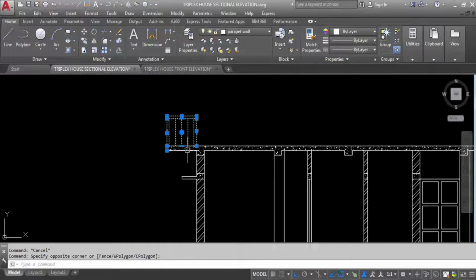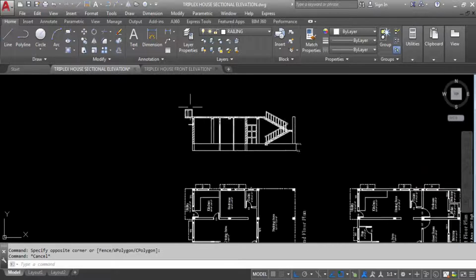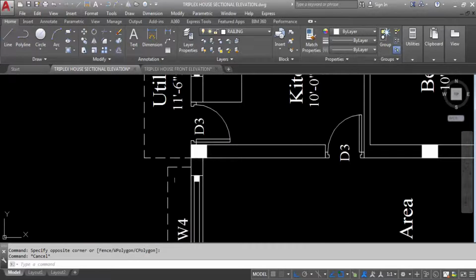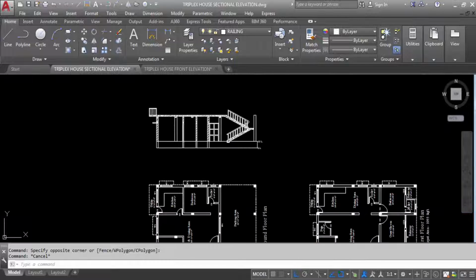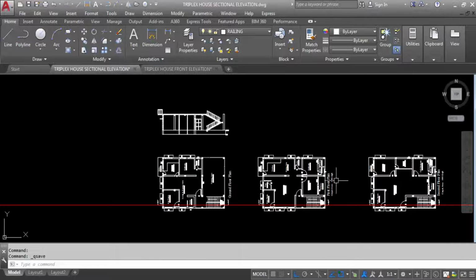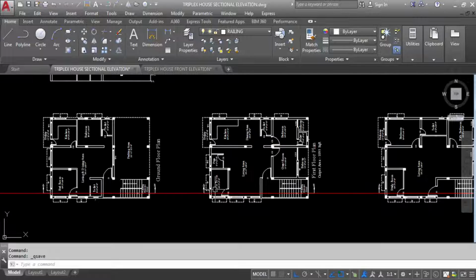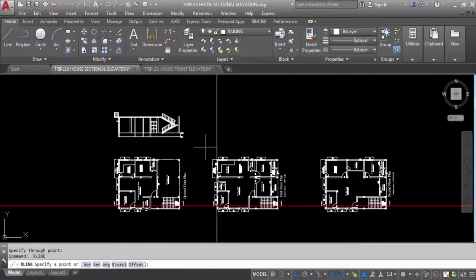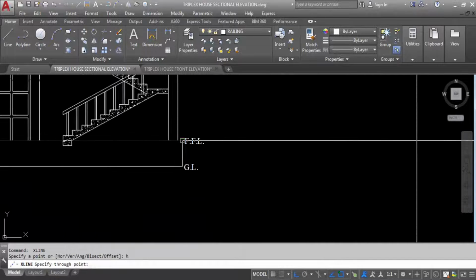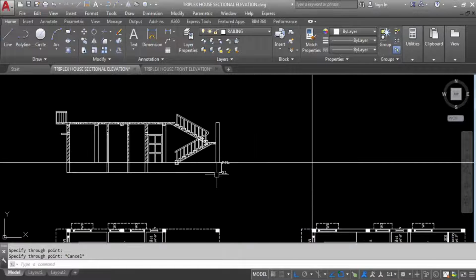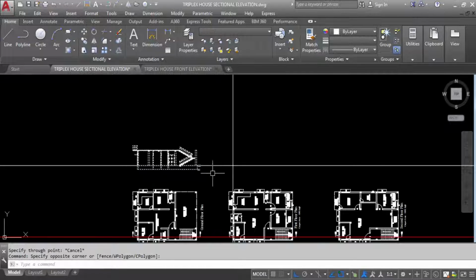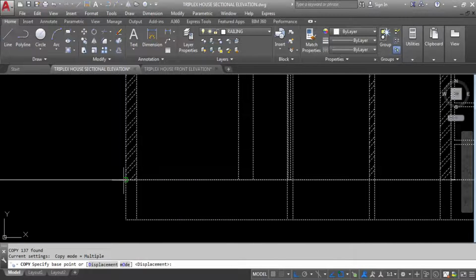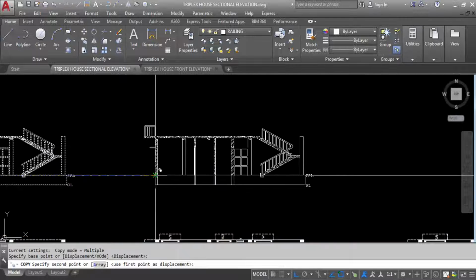This parapet wall we can see in first floor. This utility area, it will be balcony or same utility area of kitchen of first floor, and we can see the parapet wall of that. So next, the first floor. So take the vertical line and horizontal line here. Now I will simply copy this. Select, copy. This is the base point and paste it here.